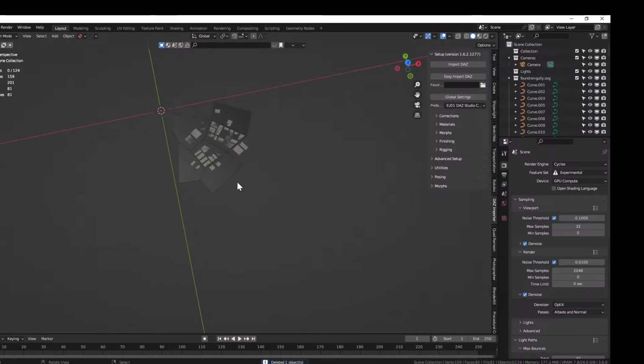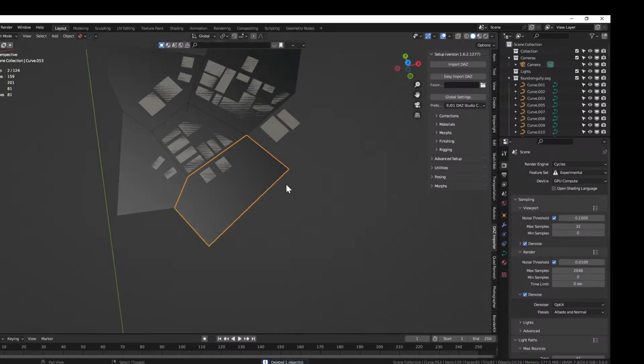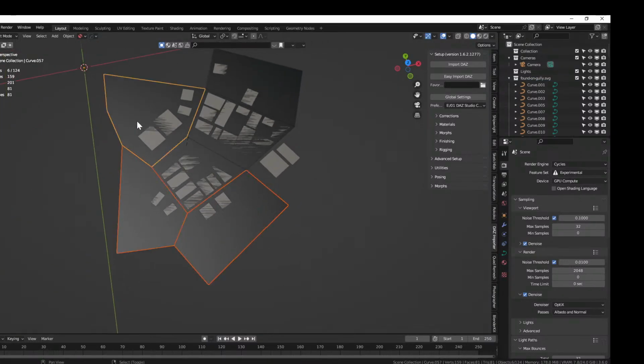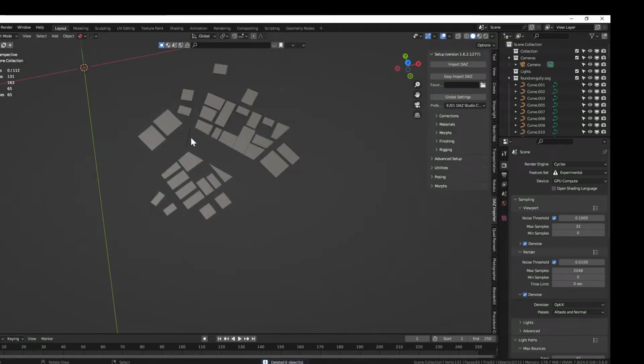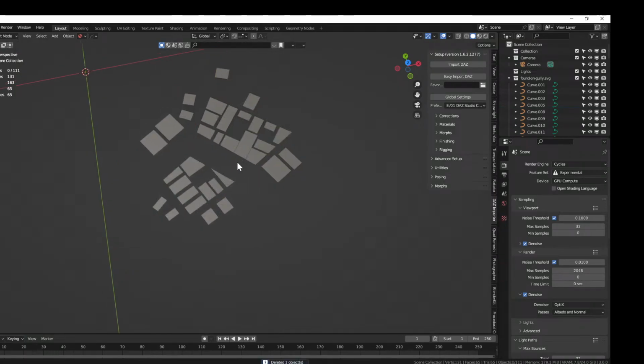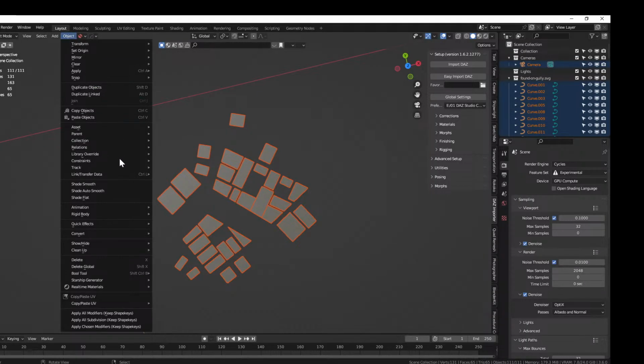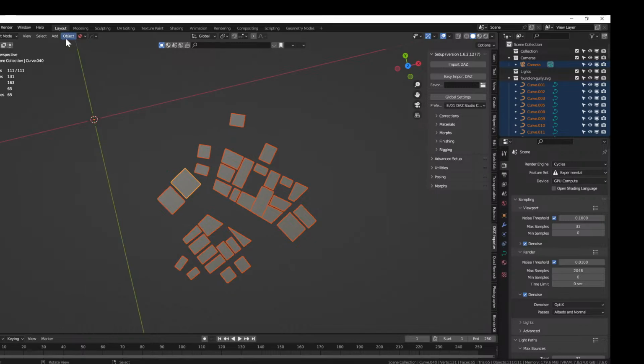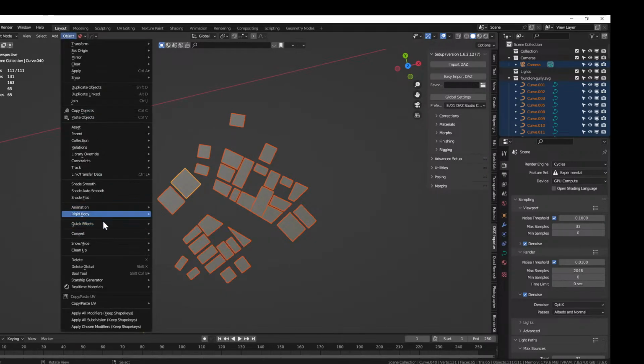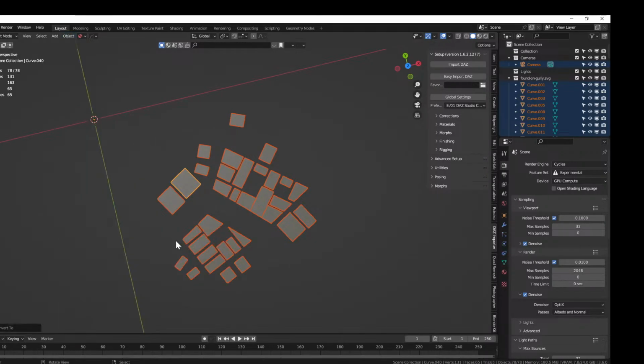And that. And you can start seeing what we're getting. Delete this, this. These are like zones. And we could actually maybe use them for something, but I'm not going to today. Delete that. And there are our beautiful buildings. Well, they're actually curves right now. But let's select them all. And object, convert to mesh. I got to select one first. Yeah, object, convert to mesh.